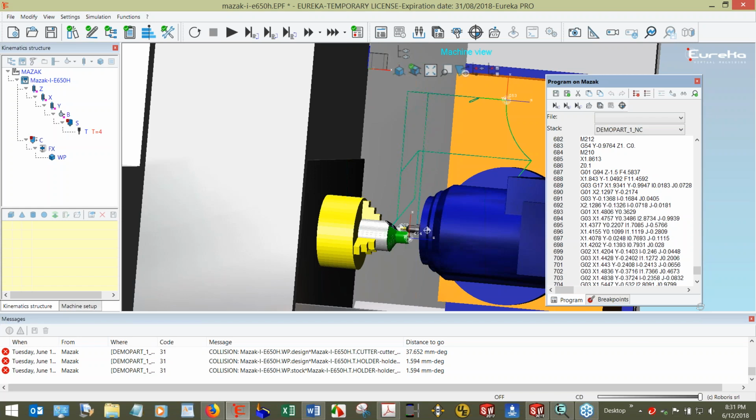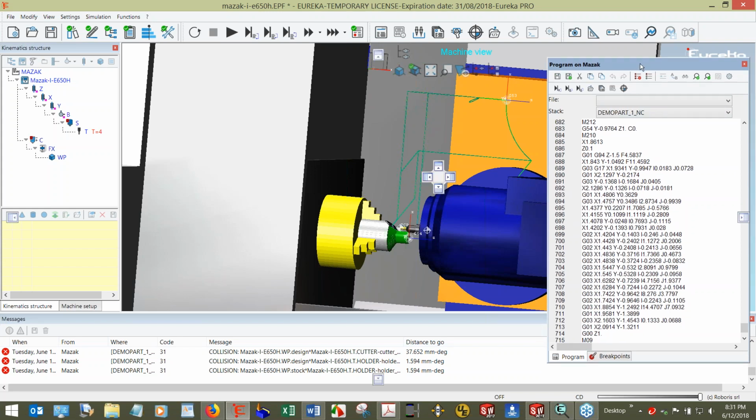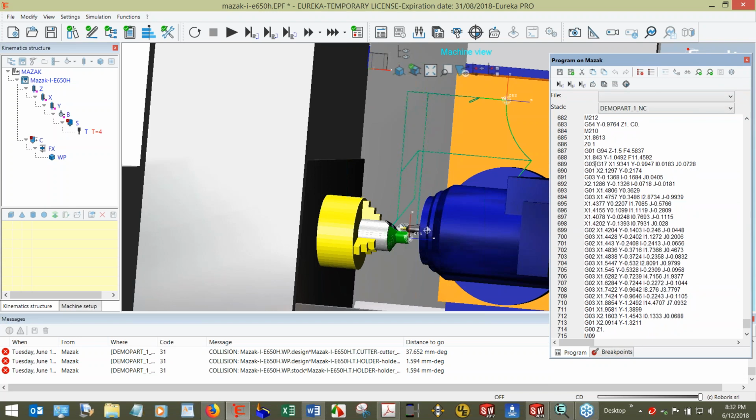Years ago, we did not have machine control operations, so things like return reference to home between tool changes got added at post-processor time. The internal simulation did not see any of that, because it wasn't something the toolpath was generating. It was generated as a function of the post-processor.